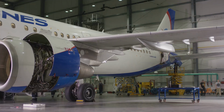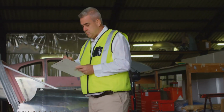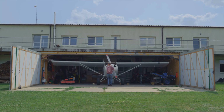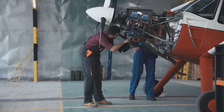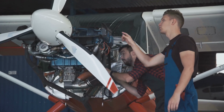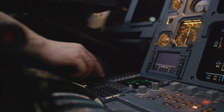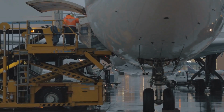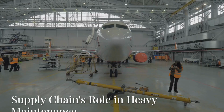This is honestly the most extensive and costly type of maintenance, often referred to as a D check or HMV, which stands for Heavy Maintenance Visit. It takes place every 6 to 10 years. Activities include things like a complete airframe strip down and inspection, corrosion control and structural repairs, as well as landing gear and engine overhaul. Those are done separately, but still coordinated. You'll also see major avionics upgrades. These checks can last up to 60 days and are usually outsourced to certified MROs, mainly due to capacity, specialization, and of course cost reasons.